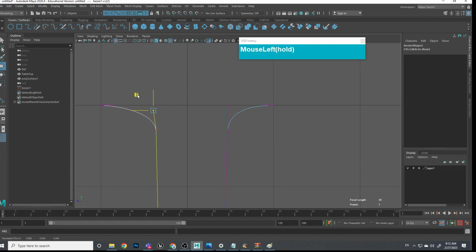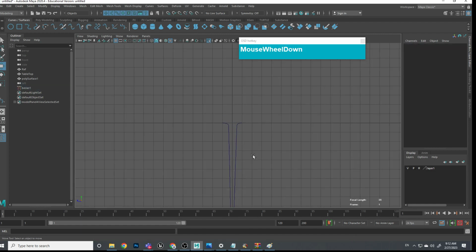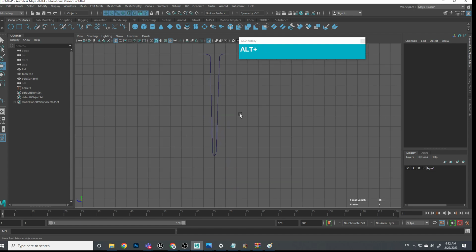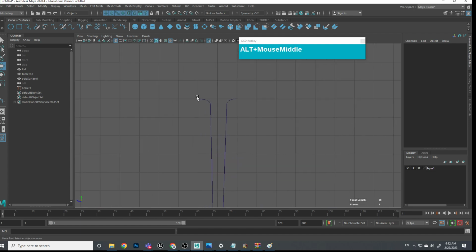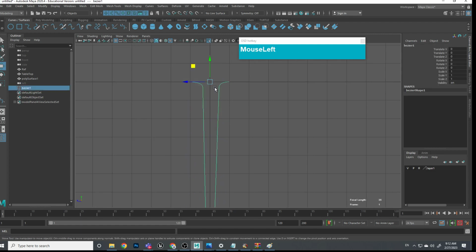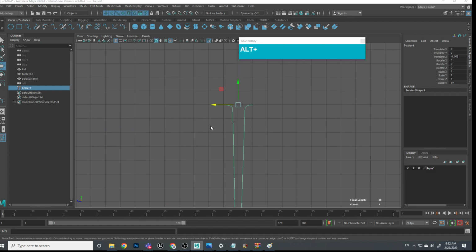So this one you need to play with this Bezier a little bit. Okay, good. So now I got the section. If I take a look at my curve, I got the cross section of the leg that is straight like that. That's what I want. Since I started drawing from here, I'm now going to select this curve and move it until the first point is at the origin, because that's where the extrude curve is going to start and then form the shape here.